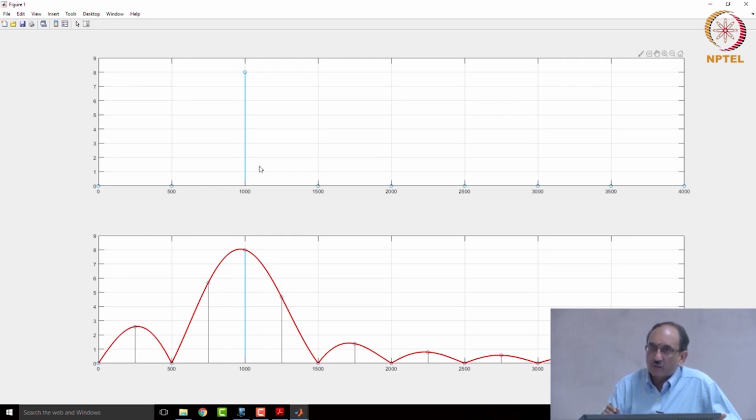if you just took the 16-point DFT and looked for peaks in the spectrum, you would estimate the peak to be at 1 kilohertz. And then if you zero padded it enough, and then looked for the peak, is the peak at 1 kilohertz or is it shifted?